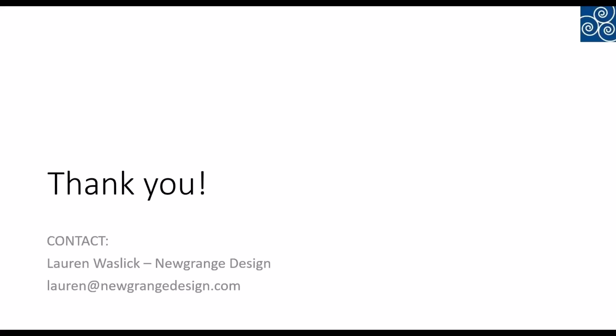That is a good question. I would recommend working with the flex fabricator on that. They're much more well-versed in creating panels, whether it is rigid or flex boards. They'll be able to help you optimize your panel and let you know what callouts you need in your fabrication drawing to maximize your use of the panel. So you can definitely panelize, but that is one of those areas where I would recommend collaboration and allowing the fabricator to give you input on what they like to see in terms of their spacing requirements and route keepouts and things like that.